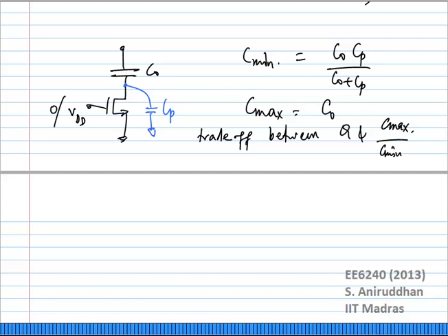Remember that mixing action which one of you was talking about? As it turns out, that has a very significant effect on the noise of the oscillator. The reason is, you have 1/f noise and flicker noise. That gets upconverted through the mixing action. Then gets multiplied through the impedance transfer function of the tank. Gives you phase noise. Okay? So actually the bias is also an important part, as you will find out when you design this oscillator. How do you design for low noise from the bias?